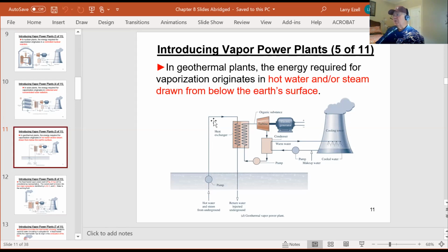To get the power down to the pump, it had a turbine on one end powered by steam. You would inject steam down hole to drive the turbine, a little miniature steam turbine about 12 inches in diameter, connected on the same shaft to the pump.